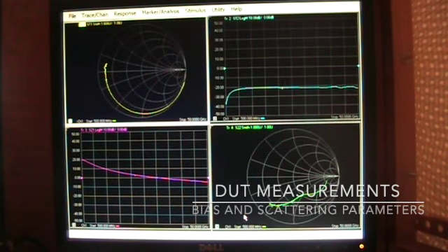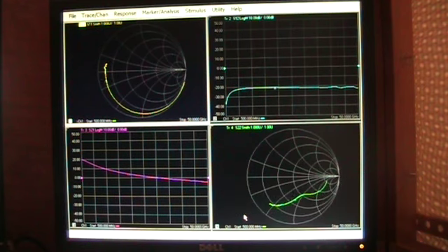We're now to the point where we can take noise parameter measurements. Presently on a state file that will allow me to see the device under test being measured for scattering parameters, and I actually have the device biased up with 3 volts drain voltage and 20 or 30 milliamps of drain current, just to see that the device is awake and alive. This particular device doesn't have a lot of gain past about 26 gigahertz. You can see that there's a little bit of calibration issues right up at the end of 50 gigahertz. That's totally acceptable. That's outside of the range that we were really concerned about.